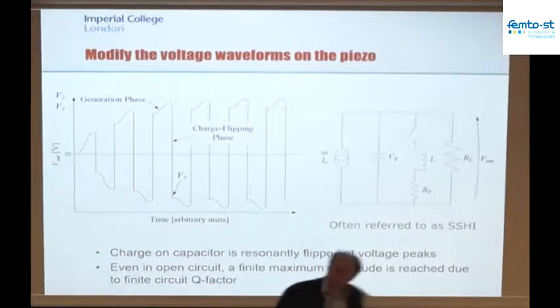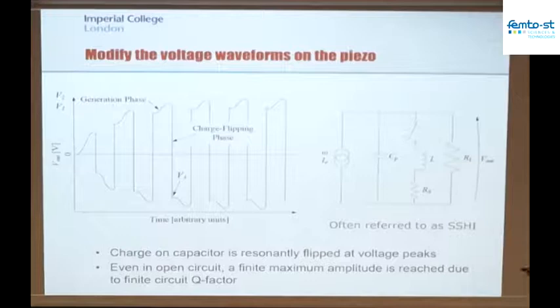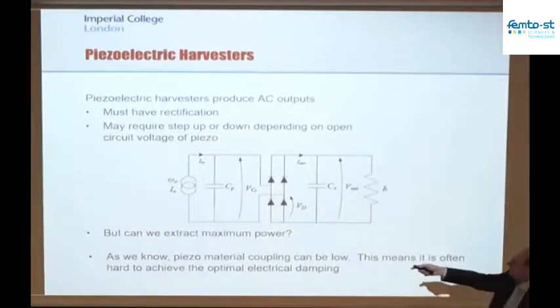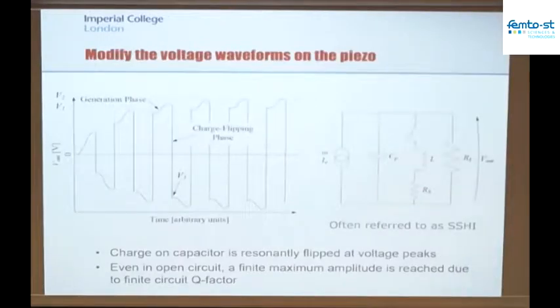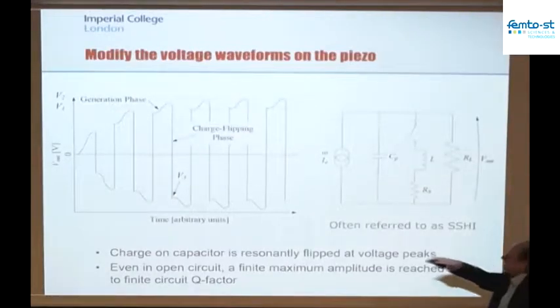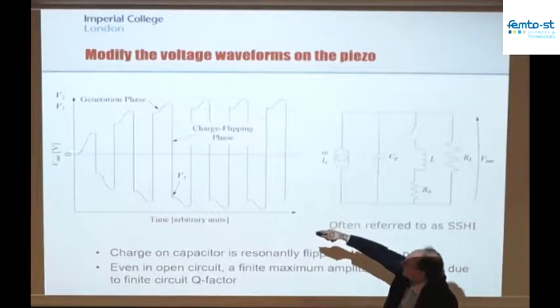And this is effectively what he showed you yesterday. He showed you something that effectively flips the charge on the piezo at different points in the cycle. He probably showed you exactly this circuit, which the people from Garimella's group, related to Daniel Guyomar's work, call synchronous switched harvesting on inductor. And the basic concept here is, rather than just take the raw output of the piezoelectric material, which is sinusoidal, put it through a bridge rectifier and put it onto a capacitor, the basic concept is to say, well, that sinusoidal voltage that I'm getting out of this piezo